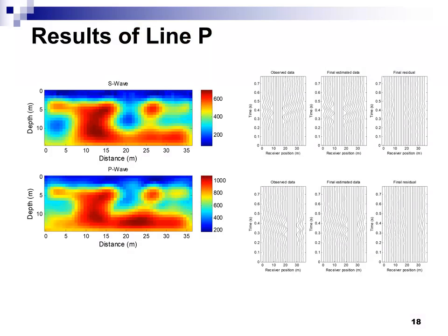And then we found 2 lines with anomaly. Line P, down to 15 meters, 50 feet depth: soil on the top, blue zone, variable limestones. Waveform match very well: observed, estimated data, residual. Low velocity zone here around 300 meters per second, so it's not a void. It's just soft material. It's next to a void.